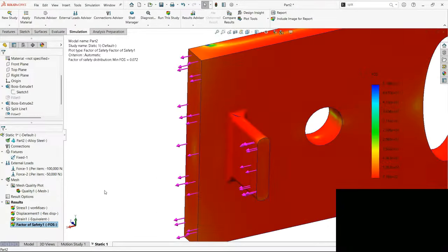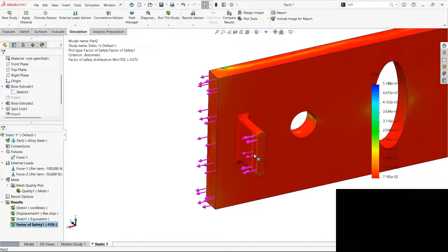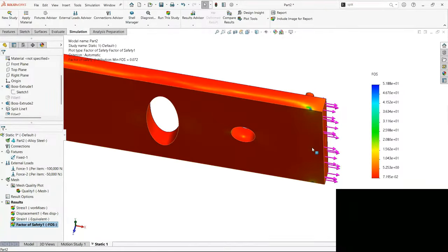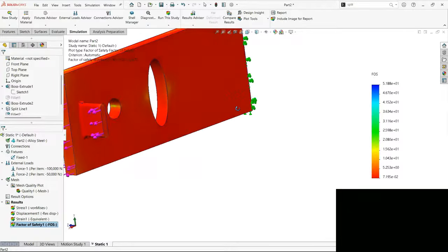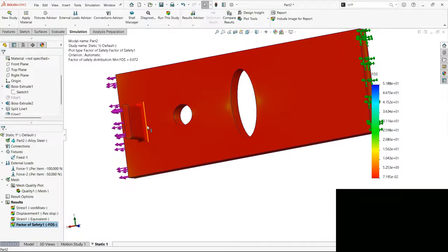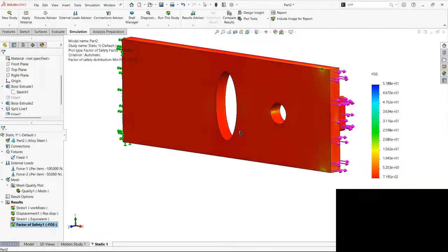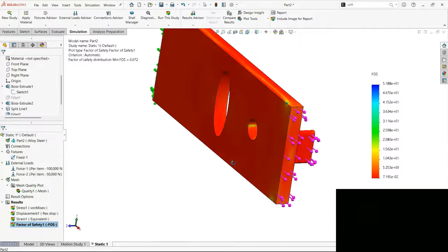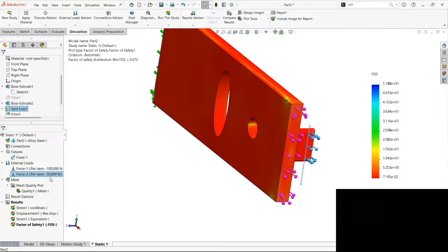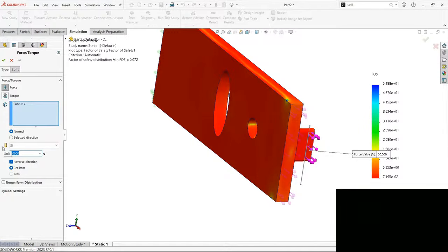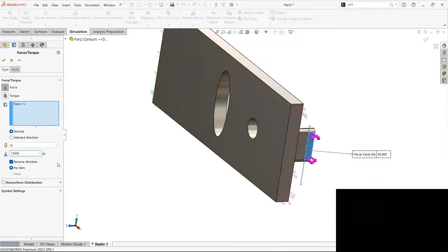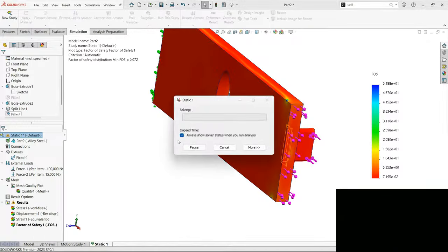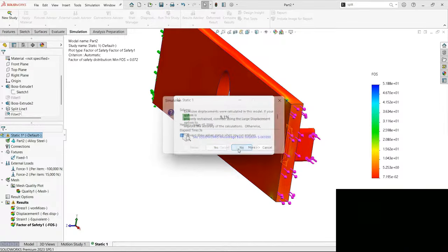If I just even switch to factor of safety, it is 0.072. The sense it is drastically failing. Okay, and these are the location where it is going to have the crack propagation, whatever it is. So actually it should be here. Now, so what we could do for this is better just reduce the value of it now just to make this analysis run. So let me just take it as 15,000. Assume this is the preferable value and let us hope this is going to help out to reduce that stress hotspot and give us the result.